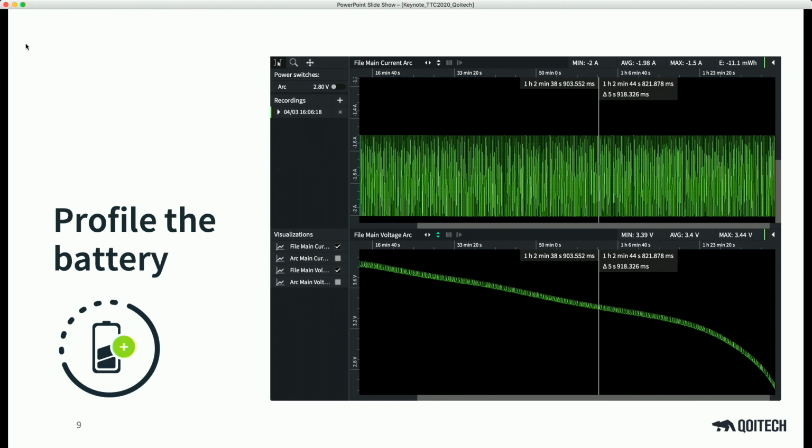So you're making sure that it's behaving according to how your application is behaving. You get discharge curves for the batteries according to what you would assume will happen in your application. And if you know that your application is going to change, you can profile it again when it changes. So you always have the updated curve, so you know whether the battery you have chosen is working all the way through your development process.